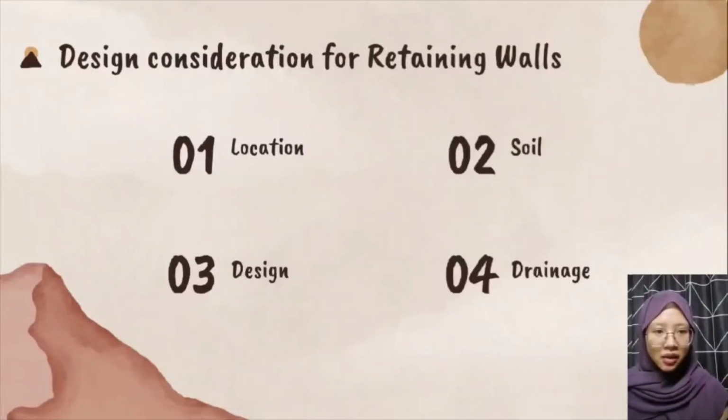Third, design. Determine the corresponding wall height, footprint size, slope, and setback angle based on the site elevation and grade to begin the design. Also, consider the natural movement of the trapped debris downslope due to gravity. Last is drainage. Ensure the wall has adequate drainage and that water does not accumulate behind it, by determining potential surface water sources and ensuring drainage near the wall location.